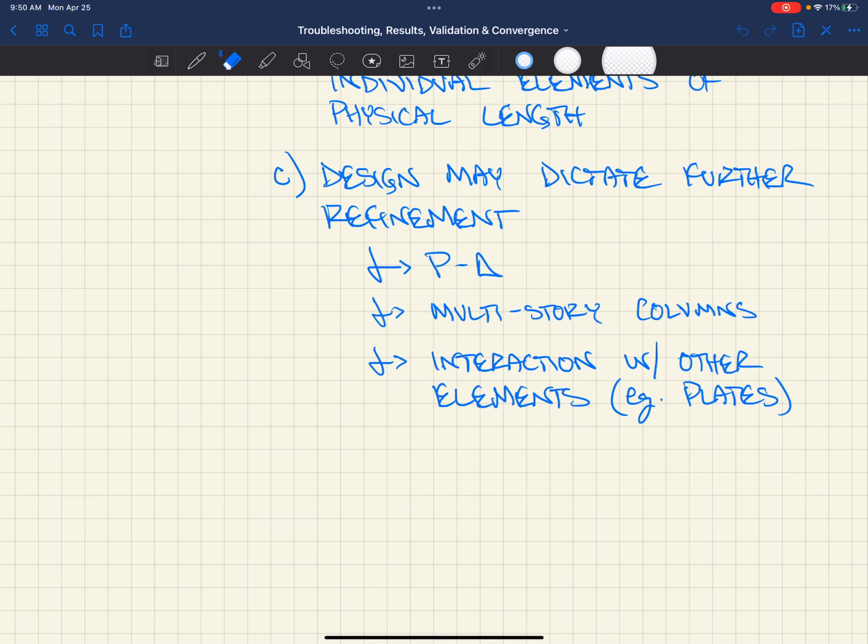If you looked in the help file in VA, we talked about how it's doing P delta, P big delta. How's it doing P big delta? Geometric stiffness matrix, right? So instead of doing an iterative approach, it's actually taking into account the fact that as it displaces, it messes with the strain energy inside the member. And so it's just doing it in one step, right?